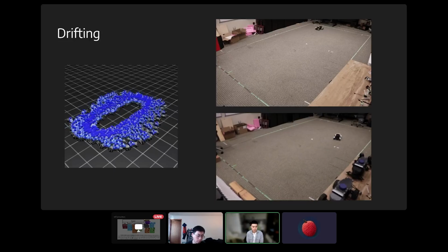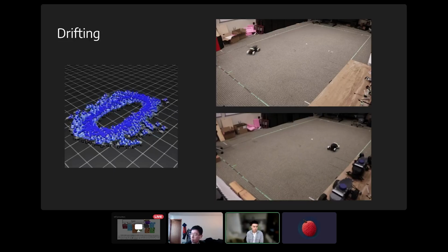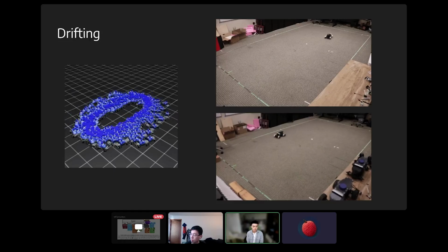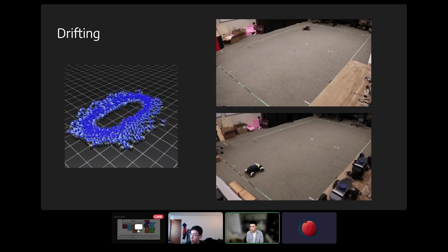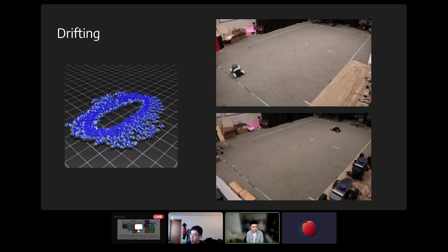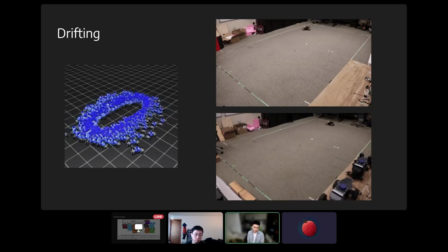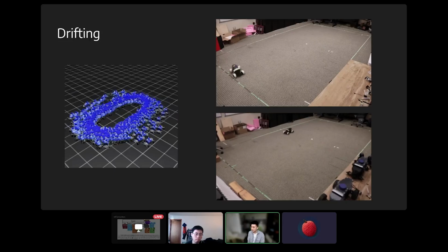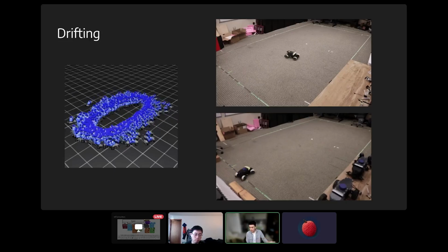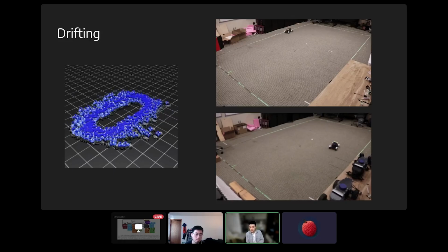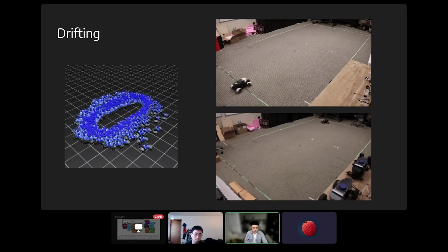So in our case, I spent maybe a week or two trying to do this through domain randomization of the mass of the robot and its tires' friction. Basically, after about a week of trial and error, training some setting in sim and then transferring it into the real world and seeing some failures.